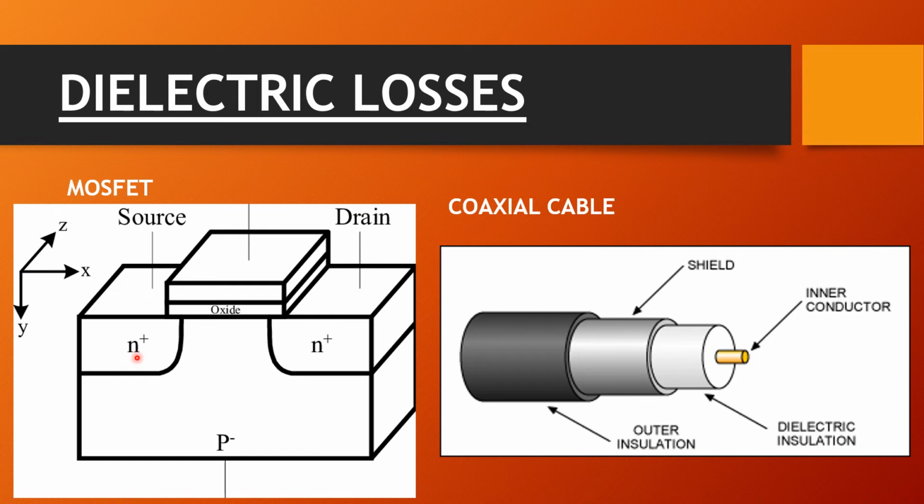Whatever it may be, if it is a P type MOSFET, it does the same thing. Source is the provider of the majority carriers and drain is the collector of the majority carriers. The same thing happens in transistors also, where emitter, base and collector are there. Base is a control electrode, whereas the emitter is the supplier of the majority carriers, and the collector is the collector of the majority carriers. So definitely, if we talk about N-type devices, the electron will flow from source to drain, and the current will flow from drain to source.